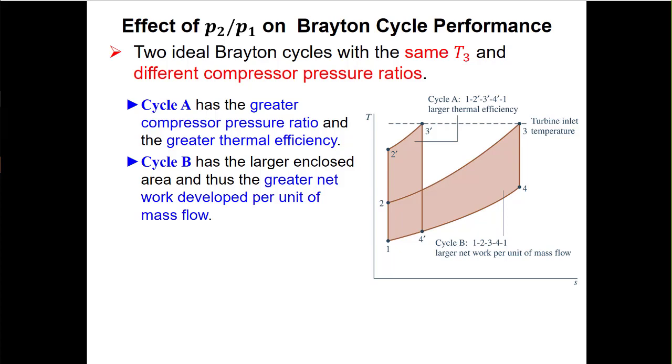So, for example, we talked about using these Brayton cycles in airplanes, and we talked about using them in natural gas power plants. In an airplane, your power to weight ratio is probably your primary concern. You like efficiency, right? But the most important thing to you is keeping that airplane up in the air. So you want to generate lots of power and you want to be light, because it's flying through the air.